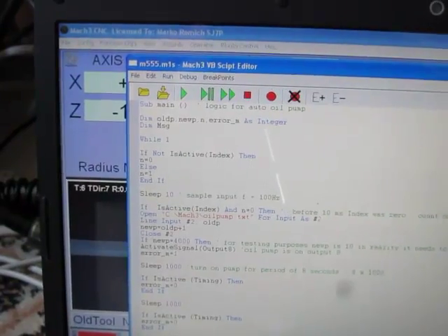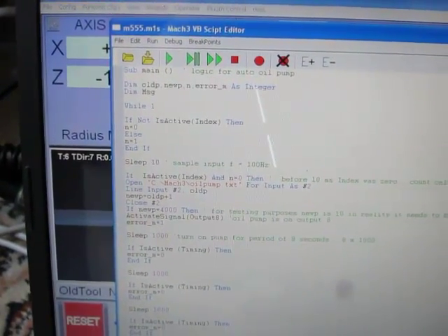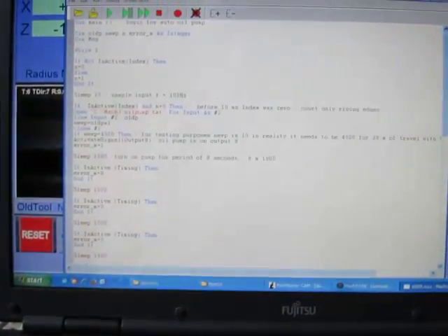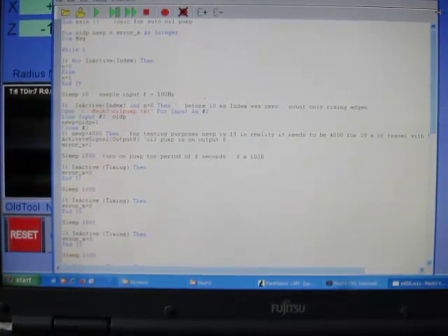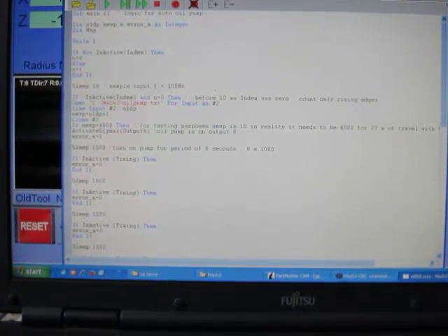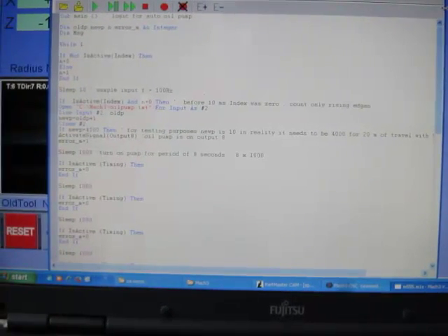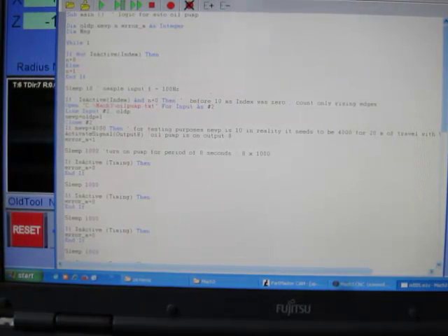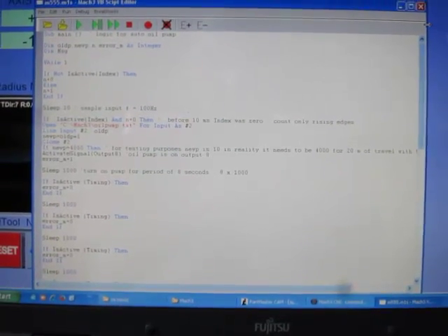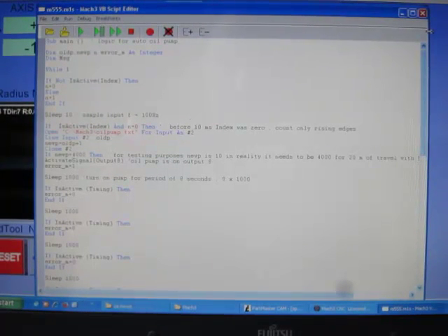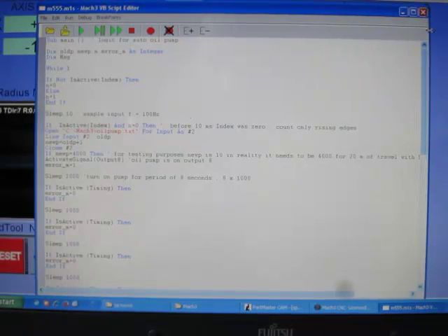So every day I learn something new. So like I said, the conclusion is that I will need to buy a PLC with fast inputs that will take care of the oil pump, if I want to monitor that after every 20 meters of travel it activates pumping for a time of 20 seconds. So this is it for now.